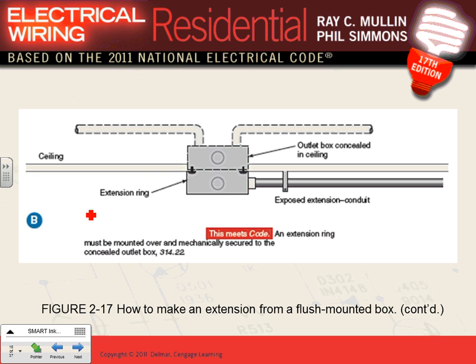So a good engineer, a good designer will choose the right wiring methods for the right application. For example, I can't wire Dunwoody with this because the code does not allow me to use Romex at Dunwoody. But believe it or not, the code actually allows you to use Romex to wire this room. You know what you need to do? Just put it inside an EMT conduit. Now, who in his right mind will put a Romex inside an EMT conduit just to wire a room like this? So when you get into the code, when it comes to residential, the wiring method of choice in most applications is Romex like these.